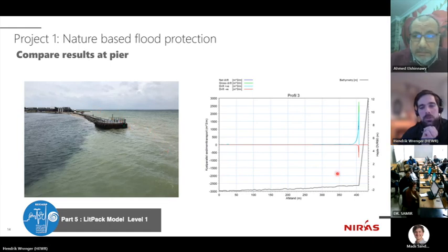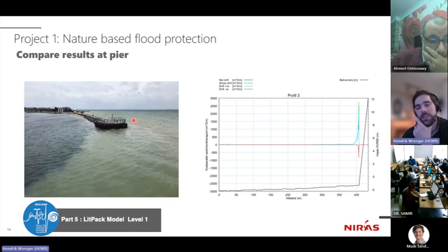So it is true. If the profile wasn't as steep but a milder slope longer out, then this would be a different picture. So although there are no direct measurements available, there are still other means of verifying, at least qualitatively, that our models are correct. Another check is whether the sediment transport goes in the right direction.